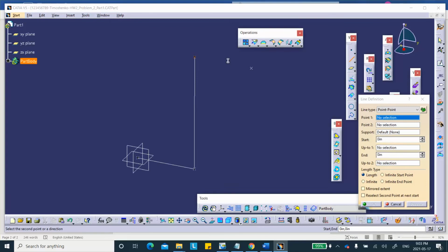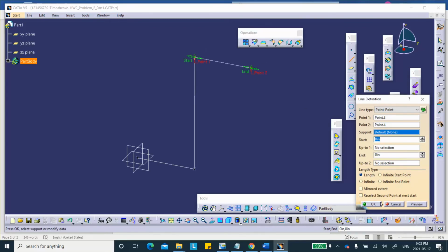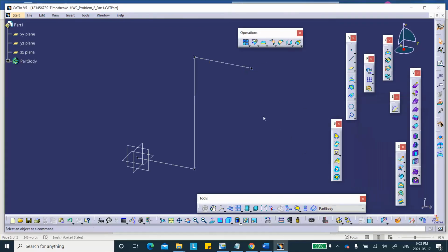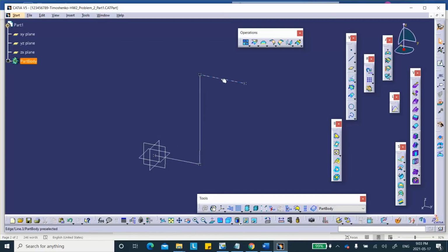And from here to there. And we say OK, and when you're done, we say cancel. And remember, I will join these. If I don't join it later on, when I mesh these, I have to do it one by one. And when I do it one by one, over here, you have a node number from this side and a node number from that side, which are different.